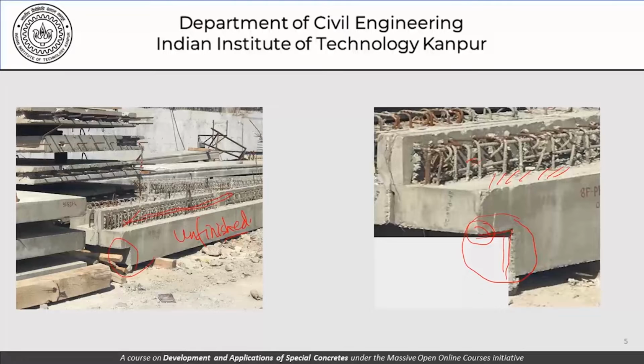So these are some of the things which are very important to bear in mind when we are talking of precast construction. In precast construction, one of the most important and critical things is joints. Now, joints is true even if the members are thoroughly finished. But here, it's not only the joints, but the casting of the remaining part of the concrete that we are talking about. So this also has to be very clearly laid out and understood. The kind of concrete to be used, its compatibility, how much time is allowed to elapse between the casting of this concrete and the fresh concrete that's going to be cast against it, because those are things which are important to determine the member behavior as such.